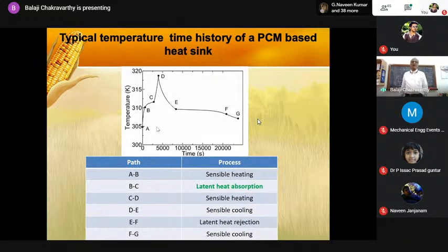You have to come up with some creative solution to attack this twin problem of stretching B to C and contracting E to F. Naturally, they will not happen simultaneously. In a heat exchanger, if you want to increase the heat transfer, it's buy one, get one free. They say, no, if you want to increase the heat transfer, pressure drop will increase. But pressure drop is undesirable, whereas high heat transfer is desirable. But there is no solution in the world where you will get all desirable things.